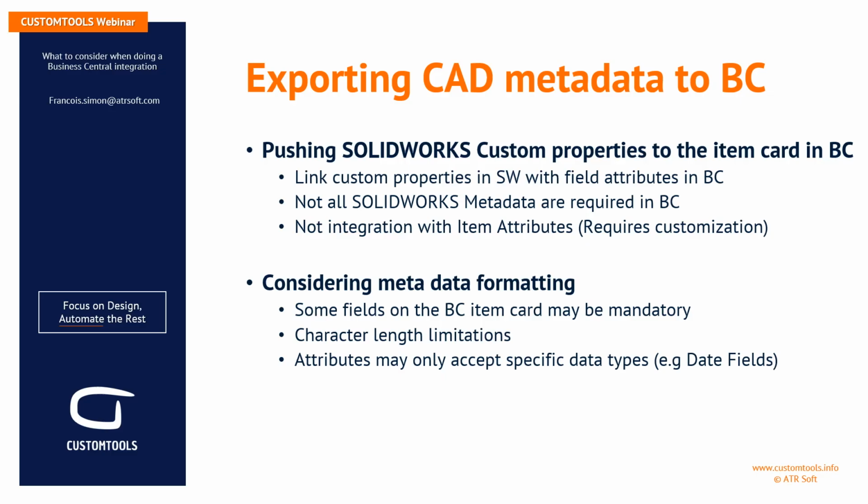During item creation in Business Central, we can also add field attributes in the Business Central item card. We can push custom properties defined in SOLIDWORKS as attribute fields of the item card in Business Central. It's very important to differentiate between what is required in Business Central and what is not. Not all custom properties defined in SOLIDWORKS need to be pushed to Business Central, as some attributes exist independently in Business Central and SOLIDWORKS.